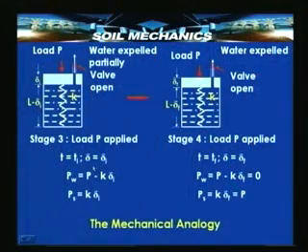Now, from stage 3 we will go on to several such stages and finally reach the last stage, where the spring is totally compressed to its final value delta_f, and the load carried by water therefore now is 0, and the entire load is carried by the solids.